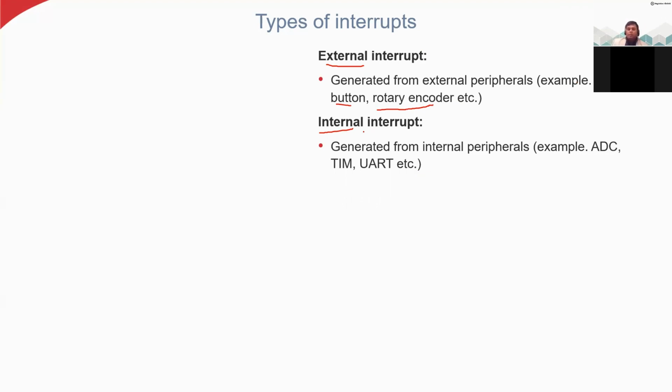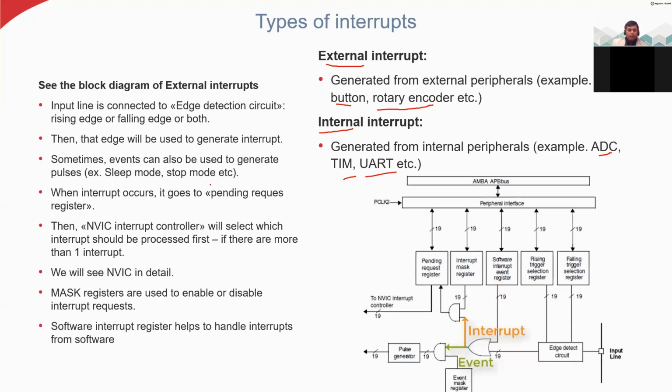Internal interrupt means the microcontroller itself has so many peripherals like ADC, timer, UART. These peripherals can also give some kind of interrupt. Then the CPU will process these interrupts. So interrupts can be coming from outside or from inside of the microcontroller.